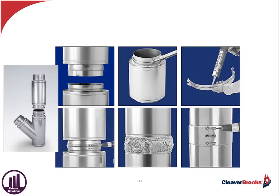There are some people that use just a flange, where you take the two sections together, and the flanges then butt together, and you seal and band them. In this particular case, it's a male-female connection. Why does that help? It helps in the overall assembly. It reduces the amount of time it takes to put these sections together.